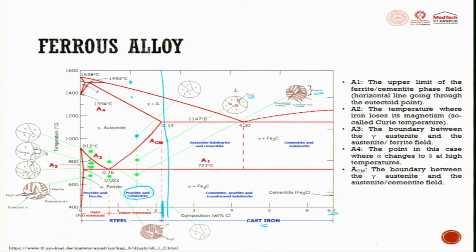In the same way, when I try to do it somewhere around here, you can see here in the austenitic phase, you have this gamma phase which is there. So, here and here it is the same. The only difference between this and this is the compositional difference of C which is getting pushed inside the iron or in the microstructure. Then I move it to the next phase. In this phase you have got Fe3C, and here whatever is getting done will be almost the same. When I further push it down, I try to get this structure all around the material.